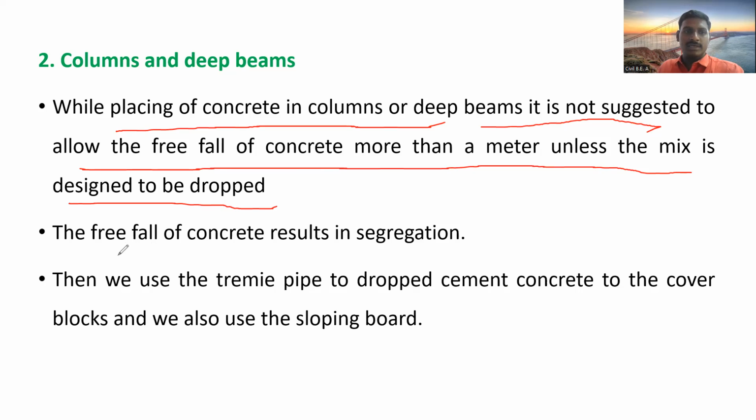Falling of the concrete results in segregation. If we drop the concrete freely from more than 1 meter height, what will happen? The segregation will happen, so we have to avoid that.